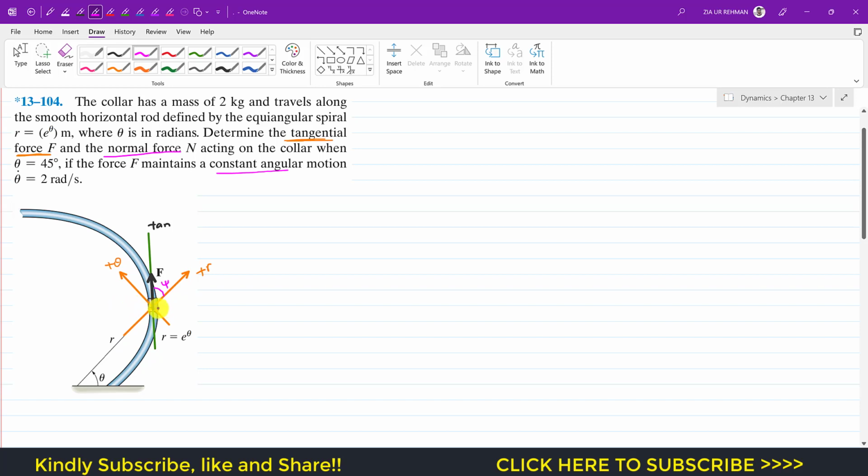Let me draw that here. So this is that N force which this rod is applying on this collar. Now as we can see, this N is perpendicular to the tangent, and this theta is perpendicular to the radial axis. So if the angle between the tangent and the radial axis is psi, then this angle is also psi.